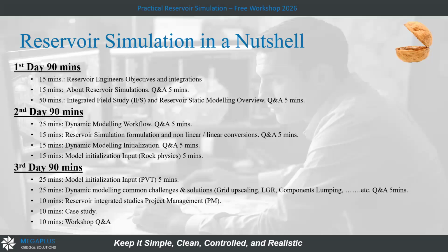And finally we discussed the rock physics, and we saw that we have homework or a task to do before we insert the rock physics as relative permeability and capillary pressure curves in the initialization before running the simulation, and the effect of the relative permeability and how the model can read these curves.